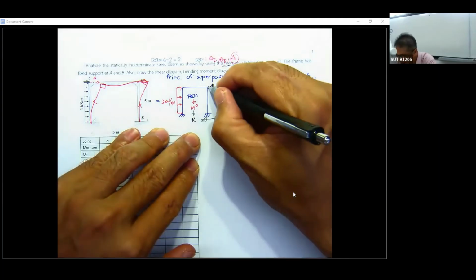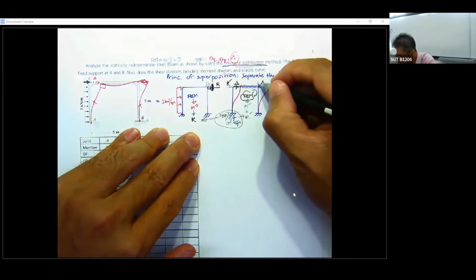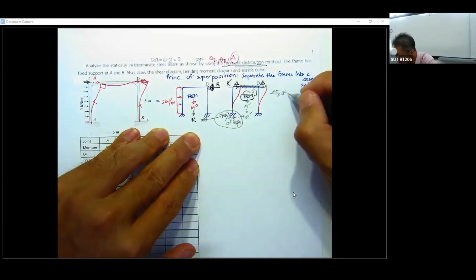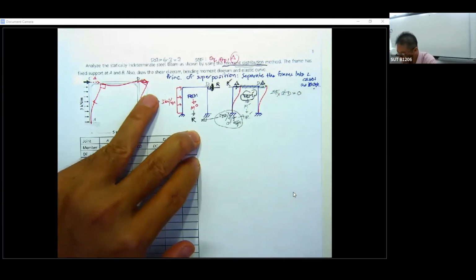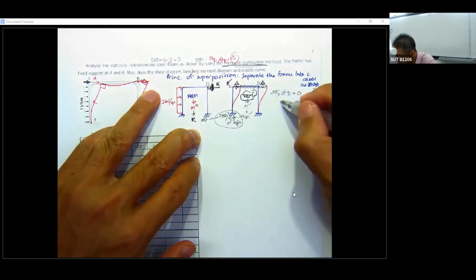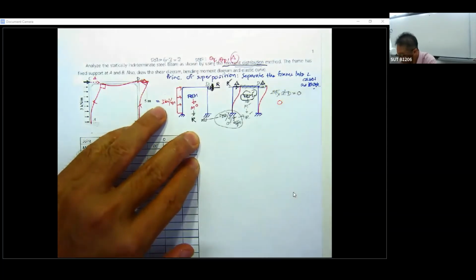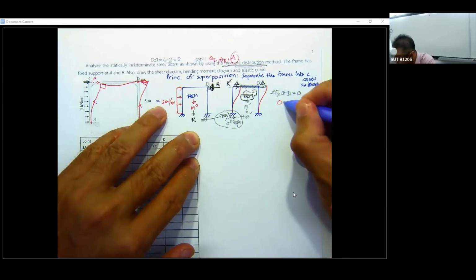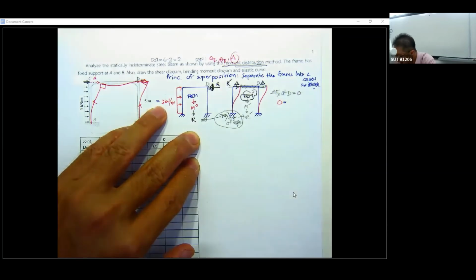Okay, both of these can be used to determine this, and then you use the summation of forces in x at this point, at d equal to 0. You can see this has no force, 0, and then it's going to be equal to R over here, and this one has the opposite direction, minus R prime, and then you have to put the correction factor due to the assumed fixed end moment.